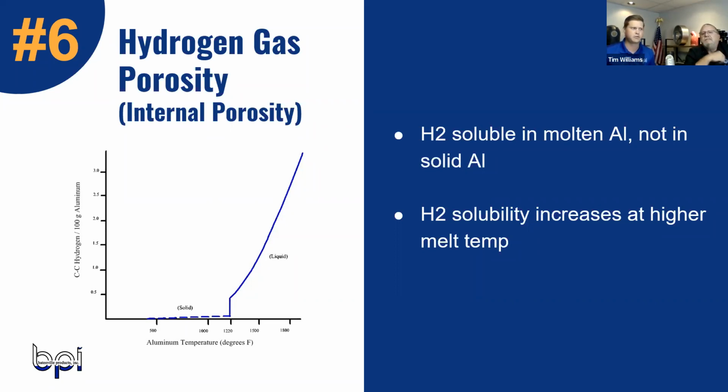Okay. So I think that went into what you were talking about earlier, Brad, that if you're putting in not necessarily bad metal, but remelt or scrap metal, does that tend to drive the hydrogen gas porosity that we're talking about here? That will drive your oxides, and if you had a high hydrogen content in your castings, yes, it could.